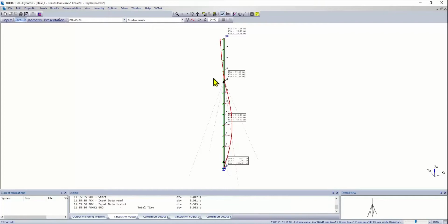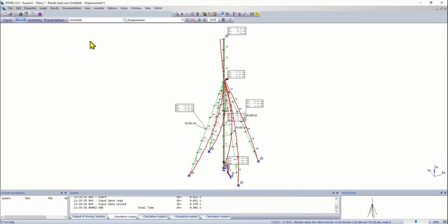So we're actually having the compressive loads due to the ropes, and this will create an additional deflection in the main chimney. And if we show all the segments now again, we can see that the deflection in the ropes itself now becomes reasonable, because now we have the second order effect, which actually creates a whole lot of additional stiffness due to the high pretension loads.